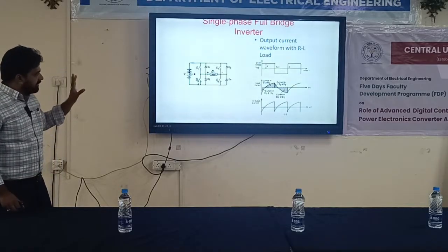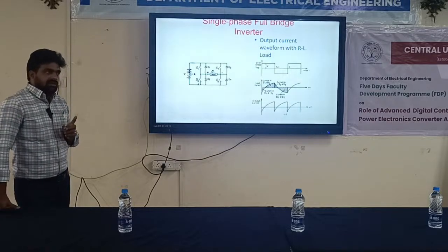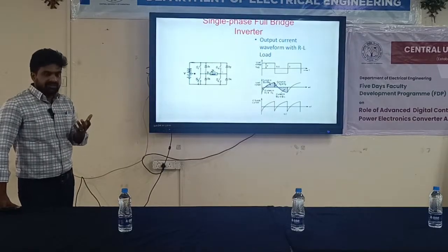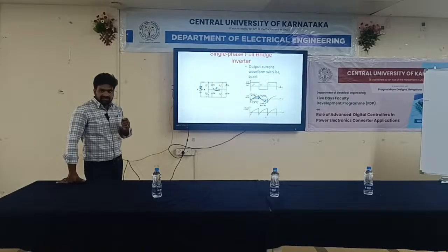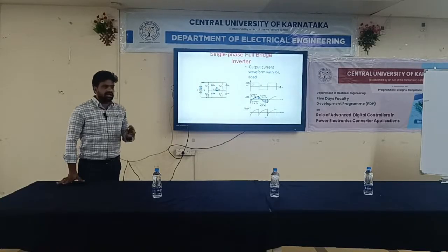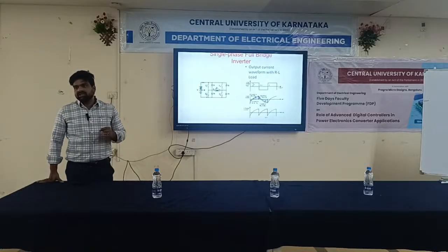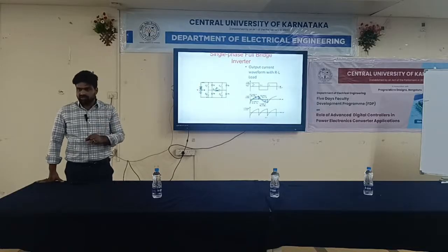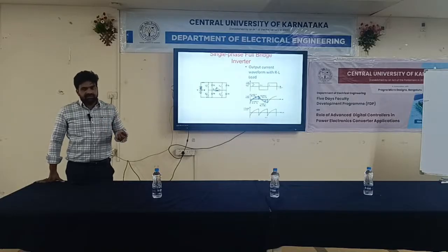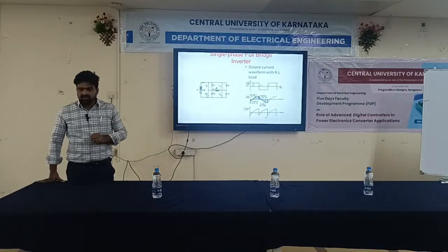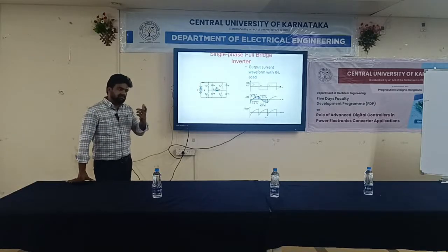But understand that. Why pole voltage is essential is, as you go in a conventional way of deciding the level of inverter, most of the studies just count the number of levels that are observed at the output side and decide this is the level of an inverter. But generally the level of an inverter should be decided by pole voltage, because when the pole voltage is symmetric in nature, it means all the switches in the inverter or the converter are going to have the same peak inverse voltage. Now, why are we specifically deciding about peak inverse voltage?